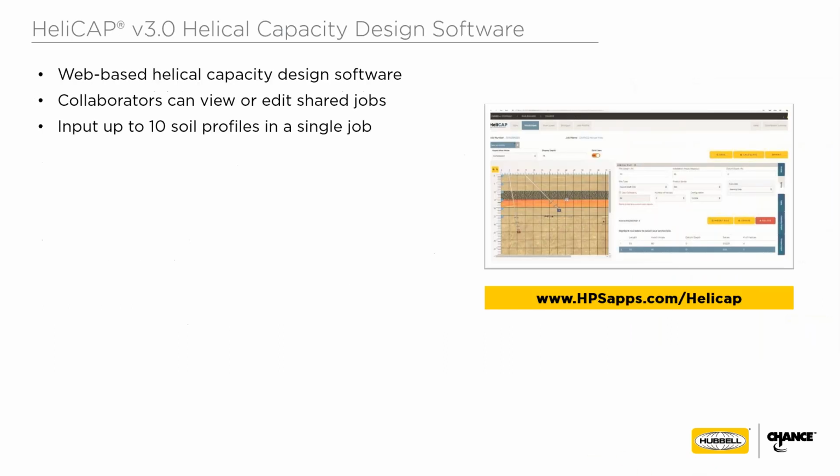Good reference. Helicap software. Some of you may be registered users of this software. This is the landing page for the software, hbsapps.com/helicap. If you don't have an account, you can immediately create your own new account. Anybody can use it. It's very useful in the design of helical anchors and piles that we've showed you today.